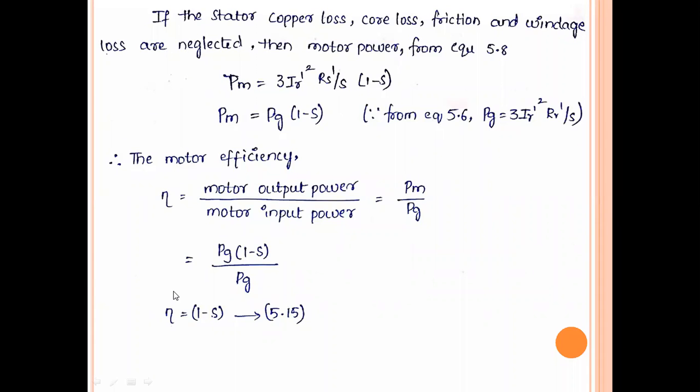Due to these disadvantages, this method of speed control, the variable stator voltage control, is only suitable for a limited number of applications where the power rating is low and the speed is also low.